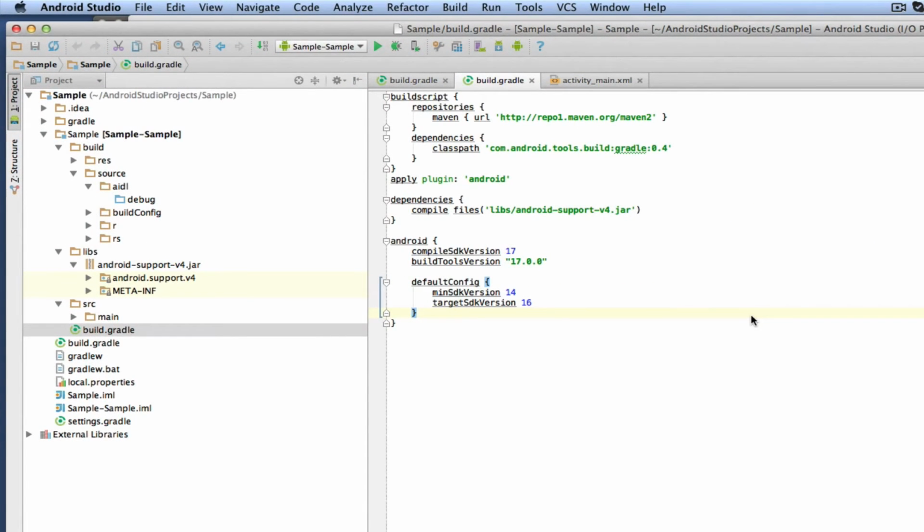One important fact of the switch to Gradle in Android Studio is that Gradle is now the single authoritative source for your build. Android Studio delegates everything to Gradle when it does its builds. Let's see how this works. I'm going to demonstrate this by running the build in an emulator from the IDE and then turning around and running the build from the command line.